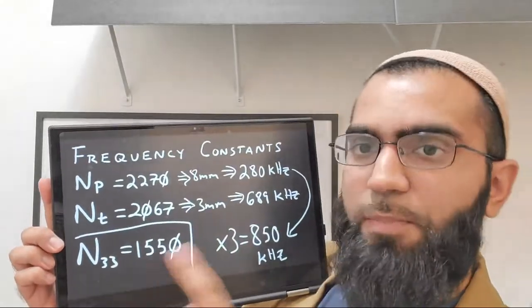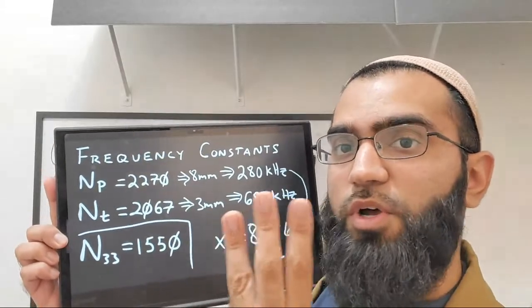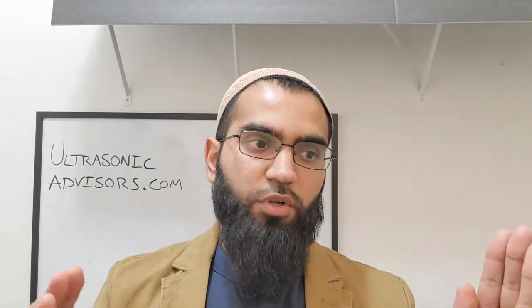So, also looking at the planar resonance, the third mode. There are two things I want to mention. The way to calculate the second resonance appearing on your impedance trace from the planar mode is that it's going to be approximately 3 times larger. It's not going to be exactly 3 times, because the planar mode is not governed by the sine function. It's governed by the Bessel function, which adds some differences, and there's Poisson's ratios in effect. But it's about 3 times larger than the original resonant frequency, and that would lead us to 850, which is much higher than the 620 kilohertz measured in practice.